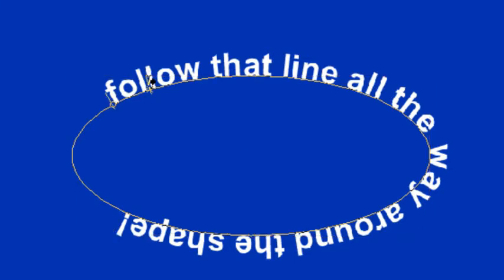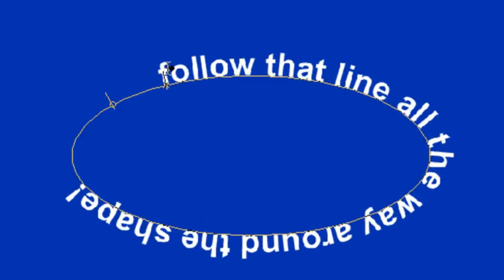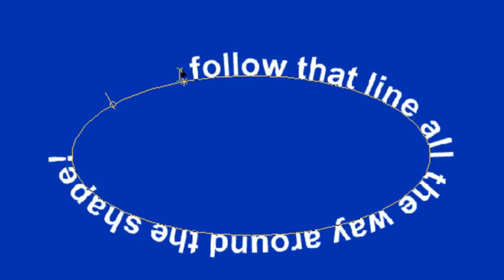And you can see how the text is following the outline of the shape that we've previously drawn. Now automatically it goes to the outside, but if we hold down the Control or Command key, you'll see how our mouse icon changes, and we can click and drag inside to actually have the text follow the inside of the shape. We can also choose to move the start point.